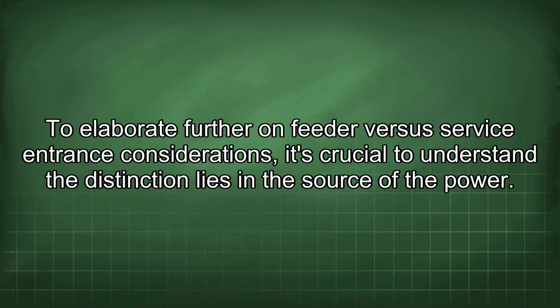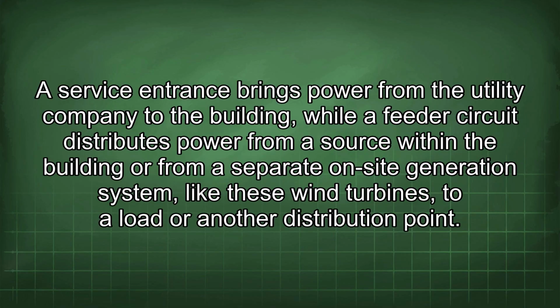To elaborate further on feeder versus service entrance considerations, it's crucial to understand the distinction lies in the source of the power. A service entrance brings power from the utility company to the building, while a feeder circuit distributes power from a source within the building or from a separate on-site generation system like these wind turbines to a load